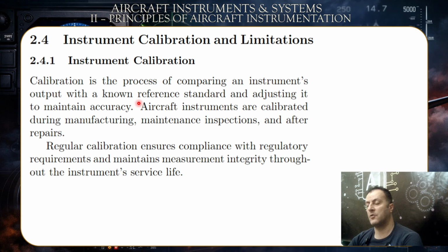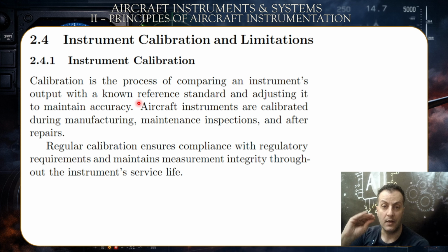The same thing for the airspeed, the same thing for the entire pitot-static system. Why? Because all measurements shall be done in reference to that point on the ground, to that current air pressure. Now, if you go into a different zone, you would have a different calibration for the air pressure, based on which you can get fairly accurate measurements.